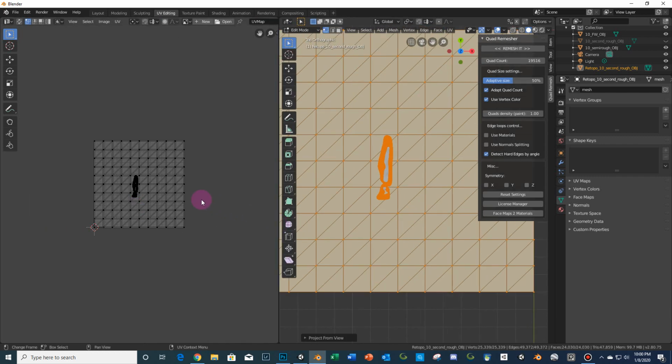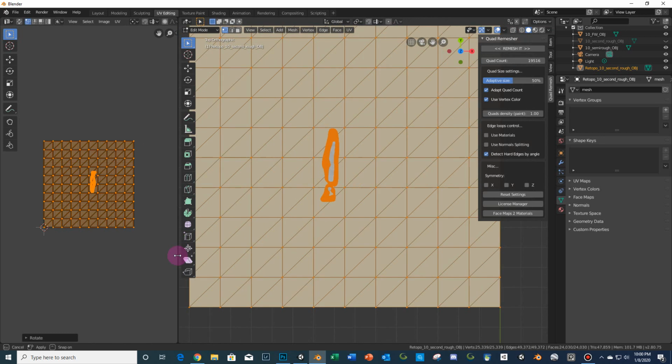Now you may want to bring your overlay in here because of the way Unity exports things with the terrains in these objects. For me, my satellite overlay is flipped 180 degrees. So you may have to do what I'm doing here, which is select the whole thing on the left here, which I did with A, with my mouse over here on the left, and then I hit R 180 and then hit enter, and then come back over here, and then we're going to unjoin these because I don't want to bring the plane in, I just want the rough. And so you're going to unjoin these by P and then choose by material.